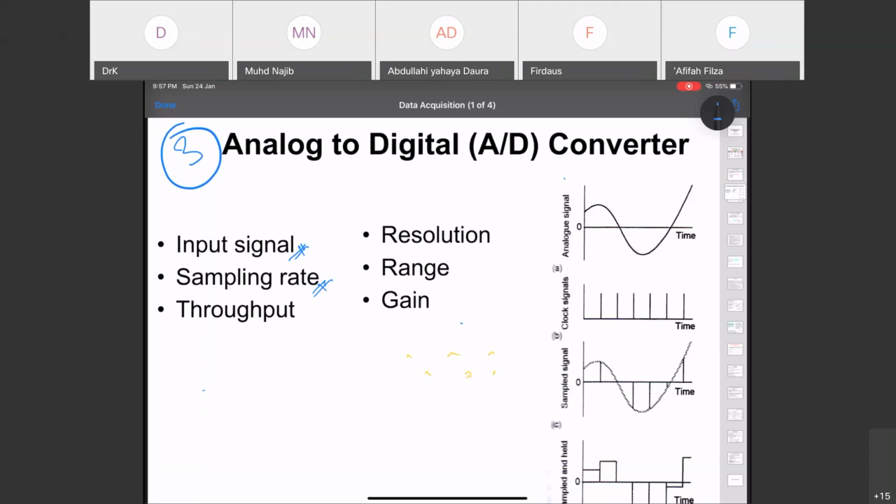And when the thing that you are measuring starts to move, starts to give some reading, you will see voltage rising, up to the maximum of that operating voltage, of that supply voltage for that particular sensor. If your sensor is operating using 5 volt from the USB, your reading from that sensor can give you from 0 volt up to 5 volt, and that's it.